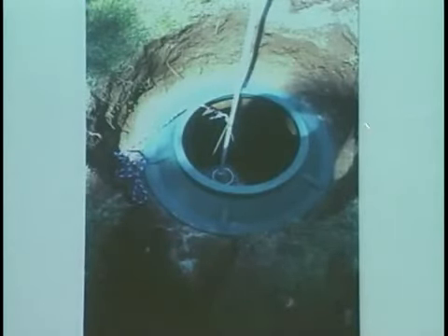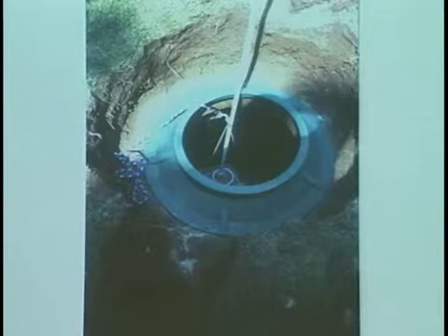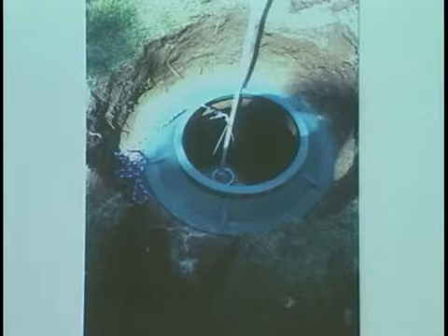There's the top of the septic tank right there. This collar goes on, brings it to the surface for the routine maintenance. And this type of system, they come out and inspect it twice a year, and each time they throw a packet of bacteria in it so that it works. And this is an aerator. It's almost like turning a septic tank into an aerobic treatment unit.